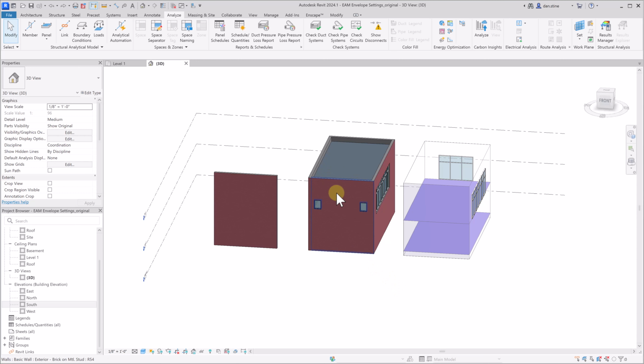We have a regular Revit elements model with a curtain wall and a couple of window families. And then we have a massing element that mimics that building elements model to a large degree, except for the punched openings or the window families can't exist. However, you'll see that these curtain walls, being coplanar with the mass element, are going to produce a model nearly identical to the building element model. And then finally, there's a wall just sort of floating here out in space.